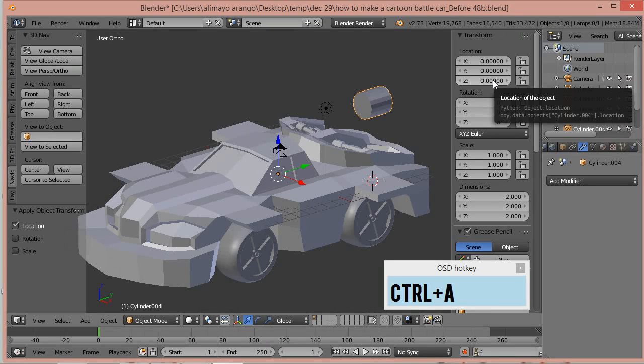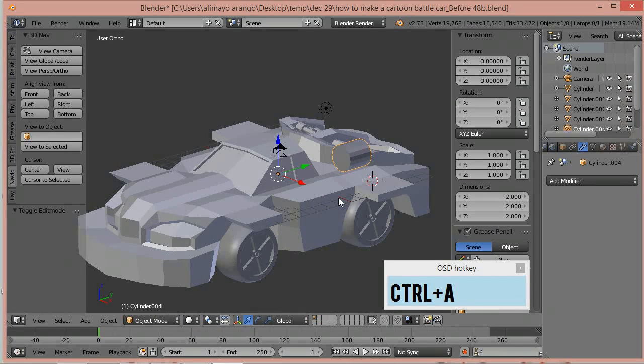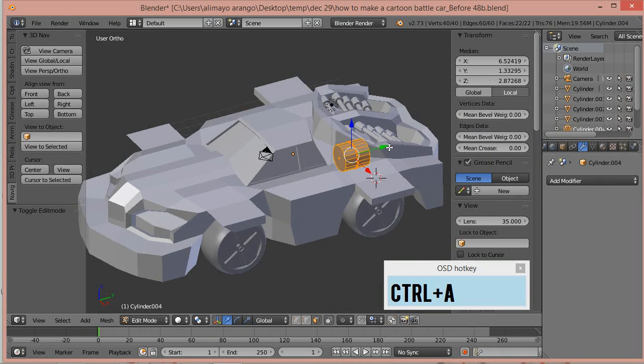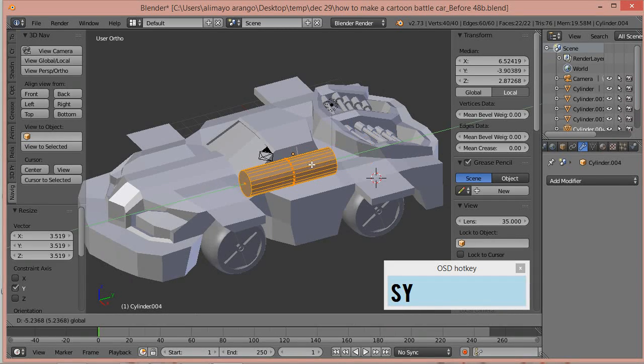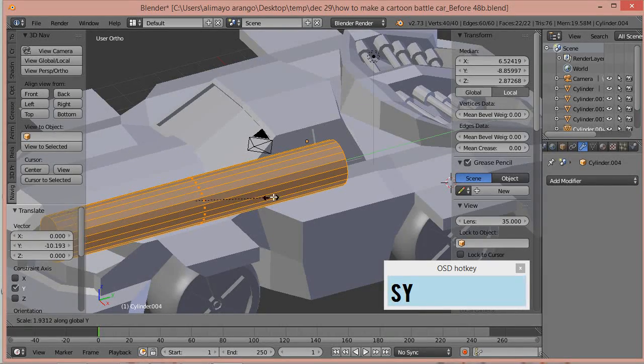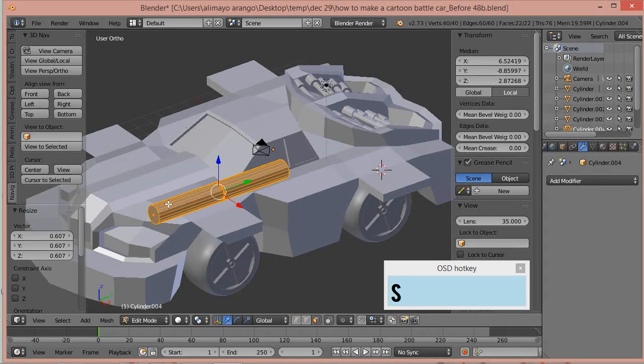So that's also typically why you'll see me go into edit mode before I move something, because I can move this in edit mode, come out, and it's still 0, and otherwise it just tends to cause problems. You're better off having that zeroed out than having the location and the global scene be something different. Anyway, I'm going to press S to scale on the y-axis here. Put this up here, and we'll press S to scale on the y-axis like that. Press S to scale, just to shrink it down some.